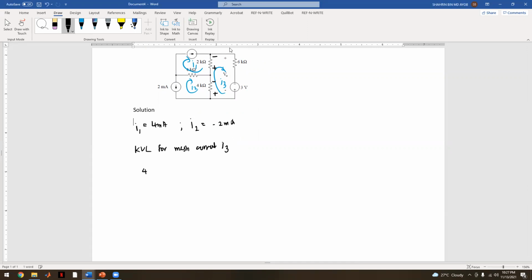So you have 4K times I3 minus I2, plus 2K times I3 minus I1, plus 6K I3, minus 3 volts, and this is equal to 0.